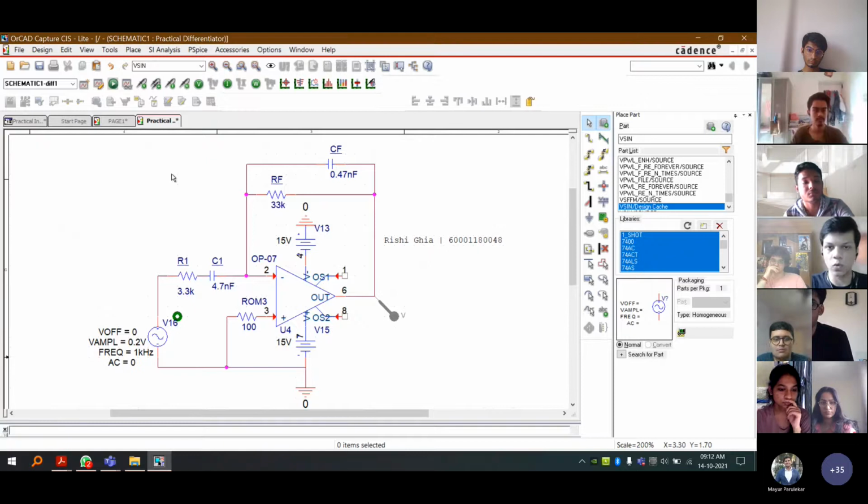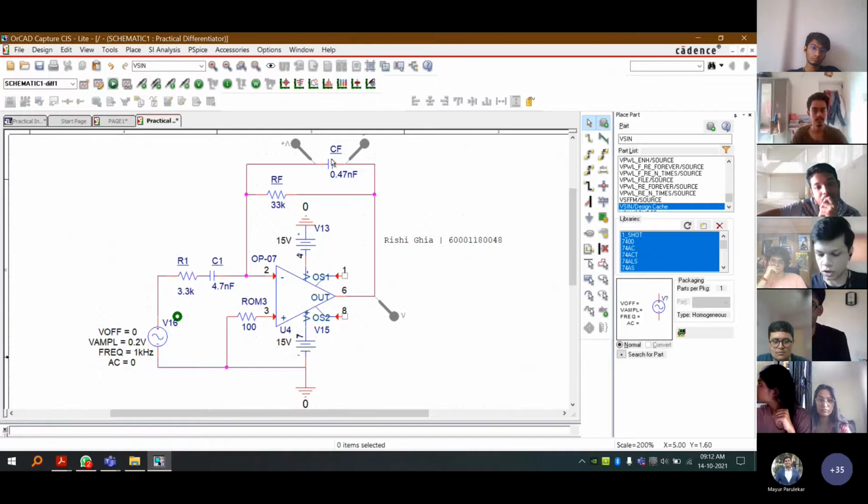These will allow us to sort of normally do in a laboratory setting. We can place one voltage marker here, and we can place a voltage marker to the right here. So this allows us to get differential voltage between these two terminals, and it will plot it within a single plot. So this is just to show you how that works, but it's not that relevant to us right now. We can just place this single pin right here at our VIN. Okay. So this is ready, and I think we can run our simulation now.